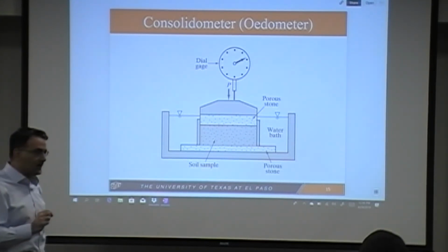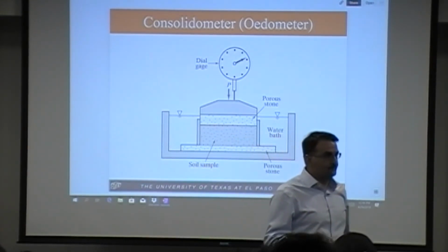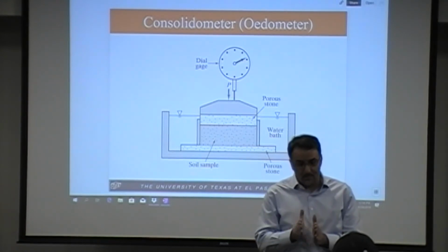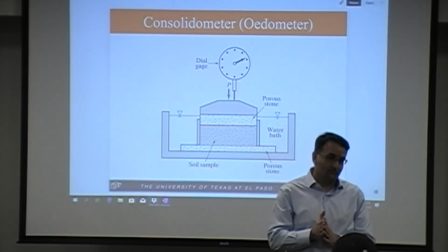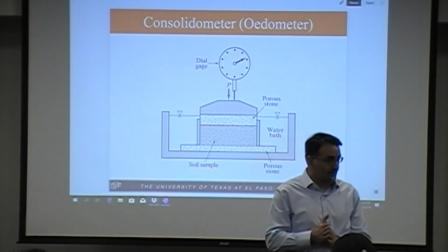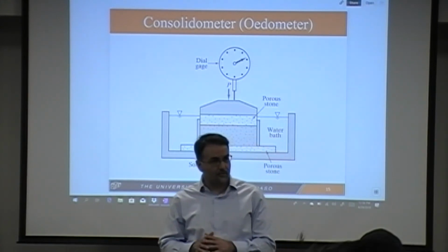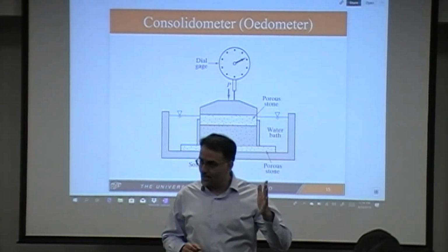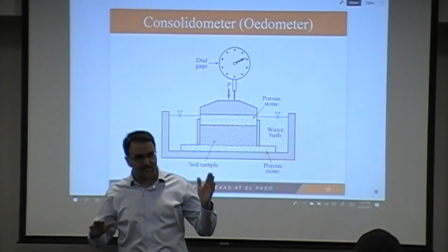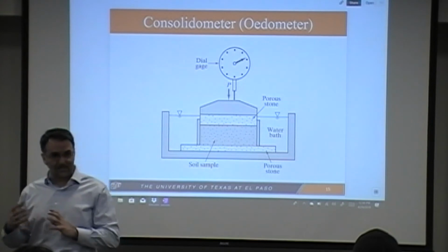It's log of effective stress. What's the significance of that? It means that it's not arithmetic, meaning that if you just misread the numbers, you might see it influence your calculation significantly. Similar to what we talked about in terms of the gradation curve. Remember gradation curve? What did you have on the y-axis? Percent passing, and on the x-axis you had log diameter, right? So that was exactly the same thing.